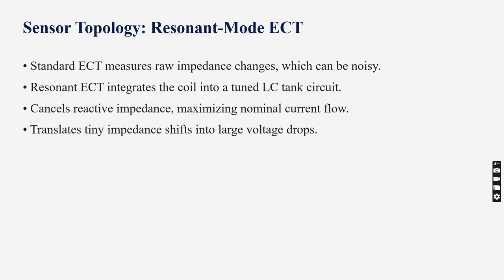Standard ECT platforms measure raw impedance shift, which is often drowned out by cable noise and temperature drift. To resolve this, we implement a resonant mode eddy current testing by replacing the inductive coil in a tuned resonant tank. The inductive and capacitive reactance cancels out at resonance.